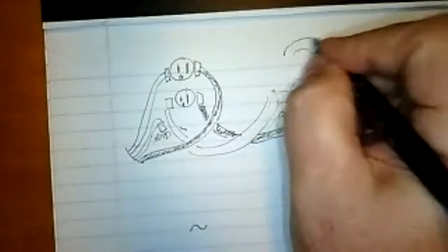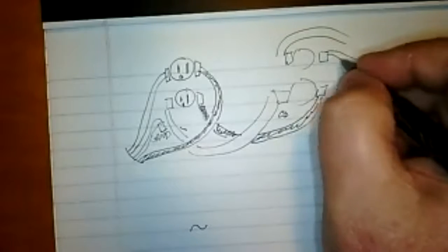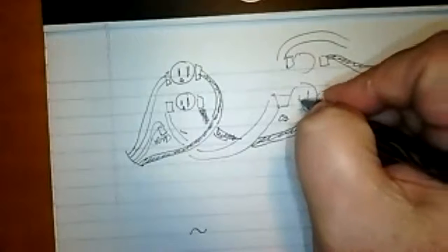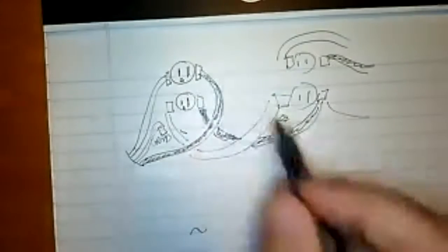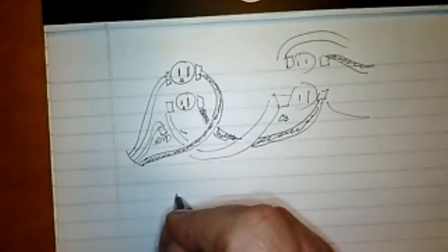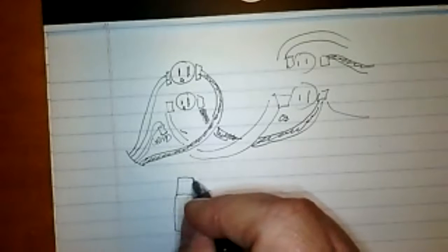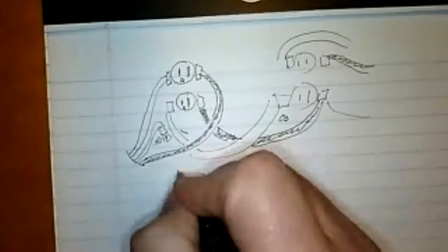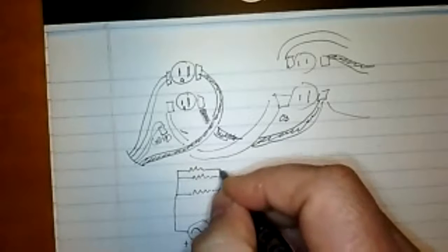We have another white wire coming from this one, another black wire coming from this one. And we can line all those up. All of our light receptacles are all rigged that way. And by having consistently the black side to the right side, what you're getting is, here's a power supply. You sort of treat this as the black side. It comes up and it runs to a resistor. And then the black wire goes to the next resistor, which again is another light socket, and another light socket like this. And then the white wires all go here, here, here, like that.